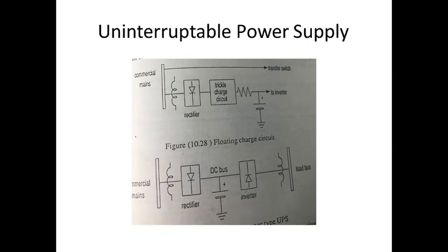The floating charge type contains a dedicated charging unit. This is energized by the line. The charger may be a simple trickle charger, consisting mainly of a transformer, rectifier, and resistor, or it may be of a much more complex design. Some models also incorporate a state of charge meter. So what is a state of charge meter?